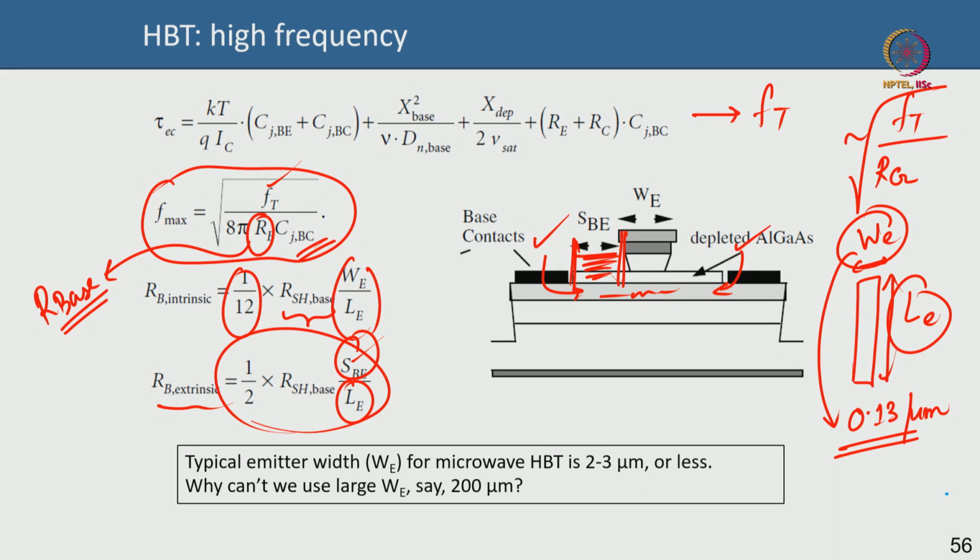Okay. So the typical emitter width, it says 2 to 3 micron, is actually a little bit old, 15 years perhaps or older. In silicon germanium or even compound semiconductor, you very much have 0.13 micron, 90 nanometer nodes. I mean, you would not say nodes for silicon germanium, but because you would be basically tagging along in a CMOS foundry, you can call it node. But in compound semiconductor, yes, you can go down really small, sub-micron, and that is how things are.